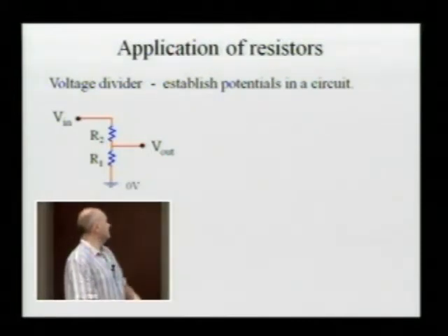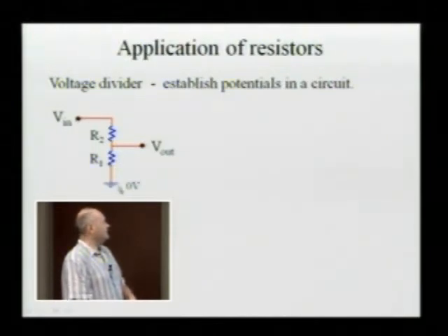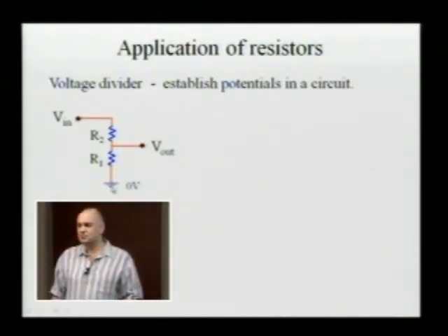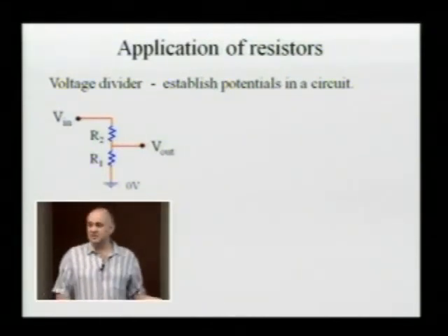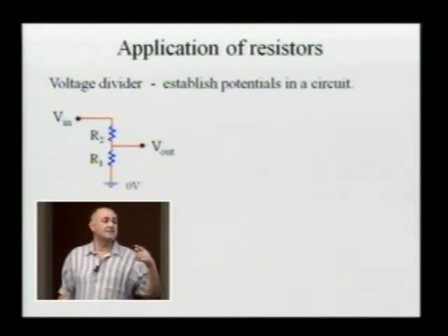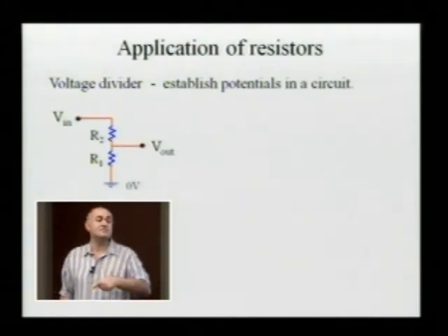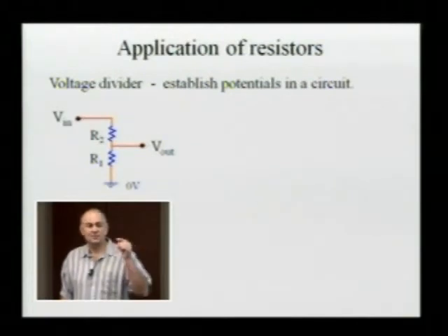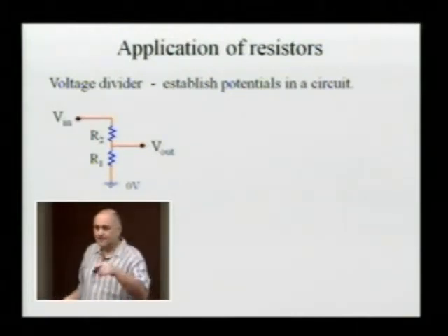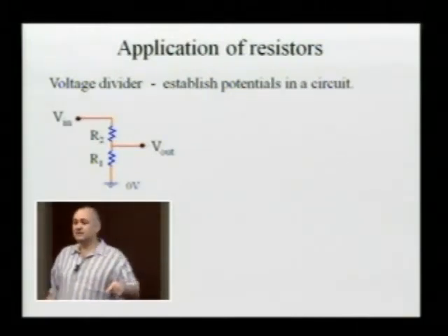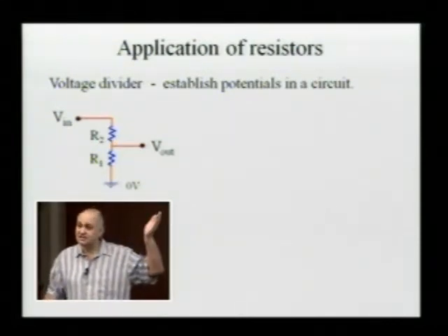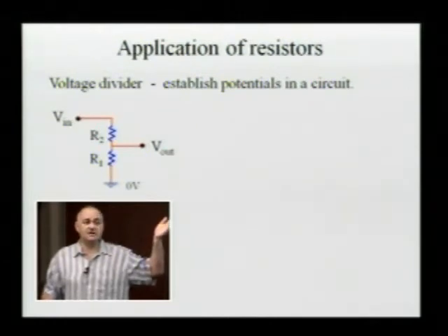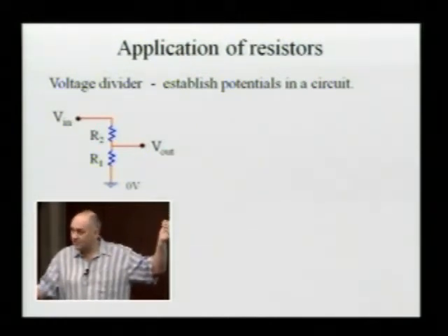So I can connect here 9 volts, and I say that I will choose the lowest potential in the circuit as the reference. So in principle, if I have this 9-volt battery, the minus on the battery, I will assign 0 to that minus on the battery. So the potential of the minus terminal of the battery is 0 because I can do it, and then consistently the other terminal will have a potential of 9 volts.